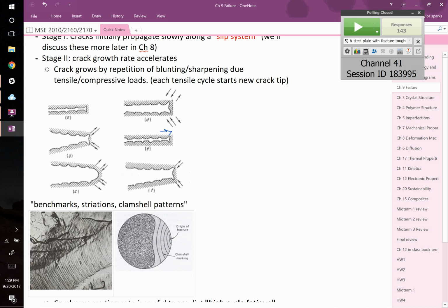So Rose's question earlier was a really good one. She said, okay, if you're cycling it between, say, positive 100 megapascals and negative 20, what's the range in stress? It's actually only between 100 and 0, because the negative part doesn't actually grow the crack. Anytime the stress is positive, we call that a tension stress, and it's going to grow over that entire range. But when it's negative, in this class, we're going to assume that it's not growing. That's an assumption that's not valid for all materials, but it's a pretty good assumption. Is that for every material or just for polymers? That's all materials. For all materials, we're going to assume in this class that they only grow under tension. Again, not always the case, but it's a pretty good approximation.